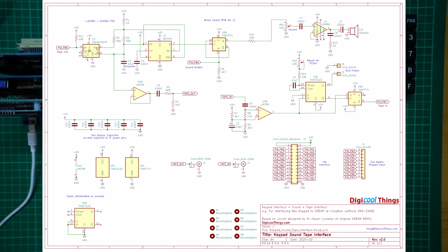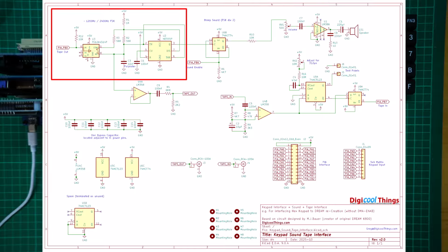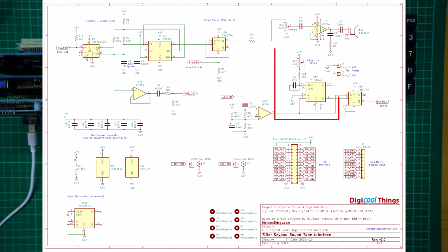Apart from this, you can see that a commonly available NE555 timer, combined with a bilateral switch, both in DIP packages, replaces the frequency shift keying function of the original NE566. In addition, I've replaced the 74121 with the relatively cheap and commonly available 74HCT123.